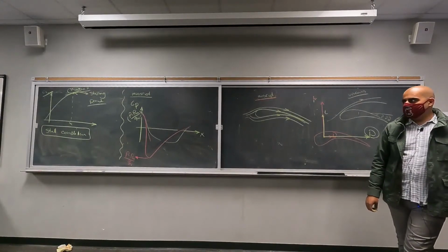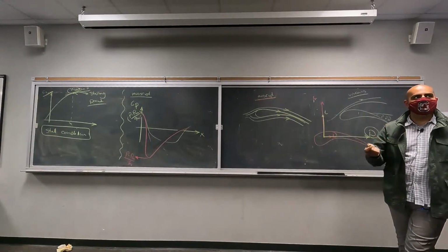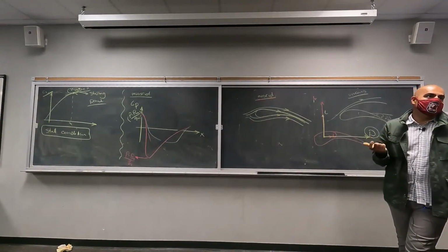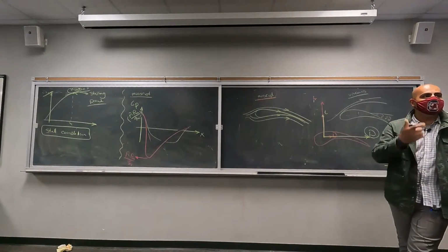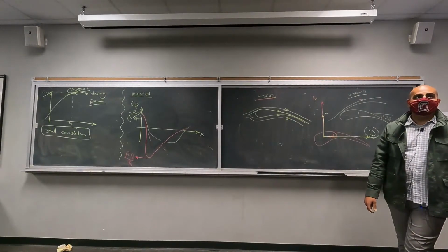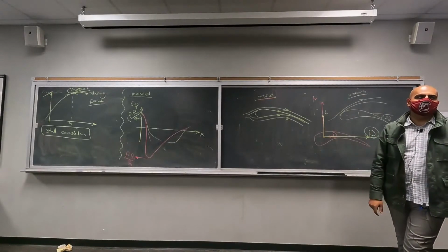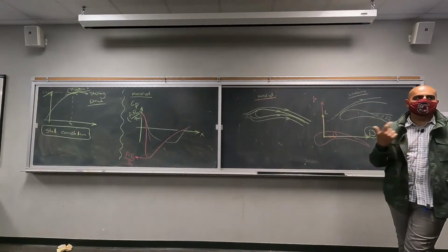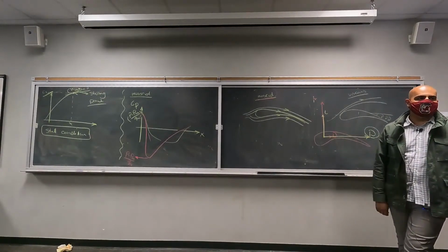So that's a very good question. We will definitely have the adverse pressure gradient, right? But the problem is that the adverse pressure gradient is not going to cause flow separation, because the model cannot see any flow separation since there's no viscosity. That's why you will get very unphysical results. At a very high angle of attack, when you have surpassed the stall conditions, running this type of simulation is very problematic. It will diverge. You have to make a lot of assumptions, help the solver a lot, and do a lot of relaxation. So yeah.